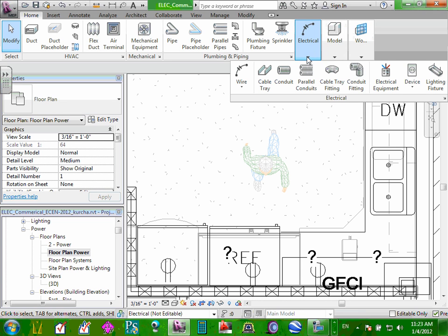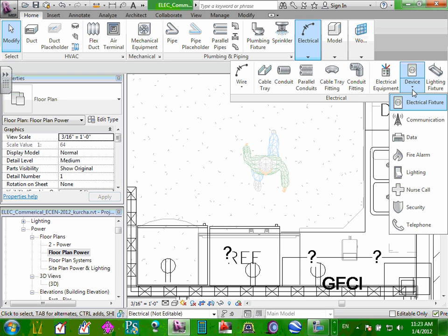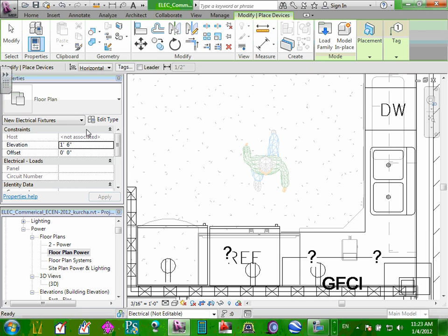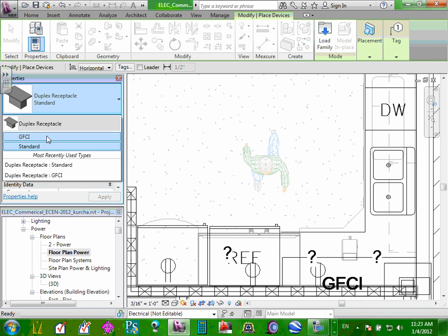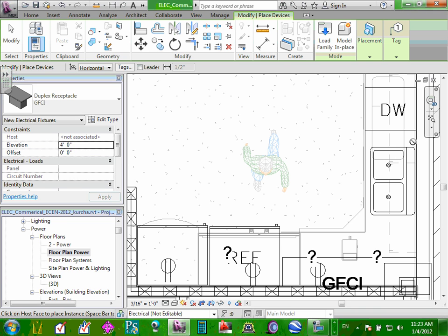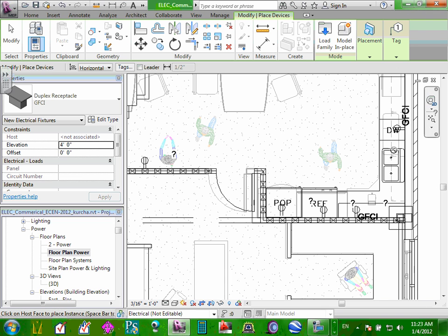Let's go back again here. Yeah, it adjusted, I believe. Let's go to GFCI. Okay, here you go, 4 feet, see it? Yep, you're absolutely right. I'm going to put a GFCI receptacle right in here. Did you guys grab GFCI even though it doesn't say GFCI on its back? You need GFCI because of the sink for the microwave.